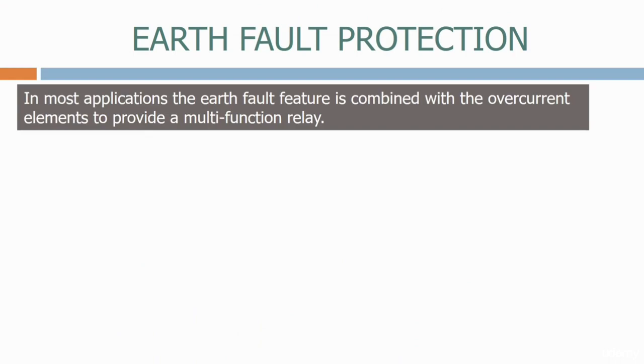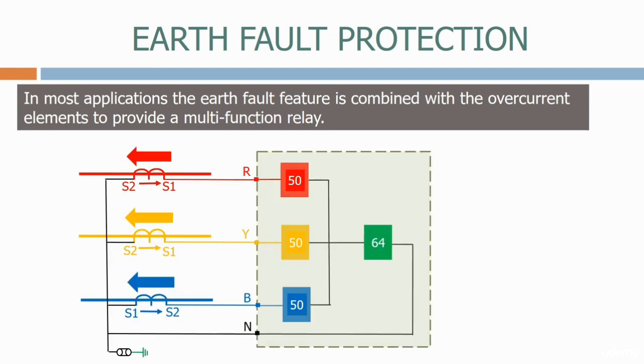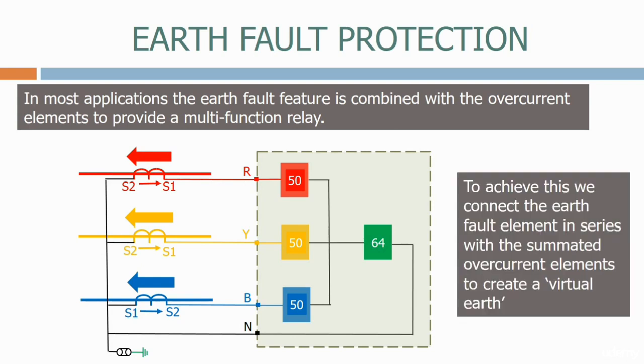In most applications, the earth fault feature is combined with the overcurrent elements to provide a multi-function relay. To achieve this, we connect the earth fault element in series with the summated overcurrent elements to create a virtual earth.